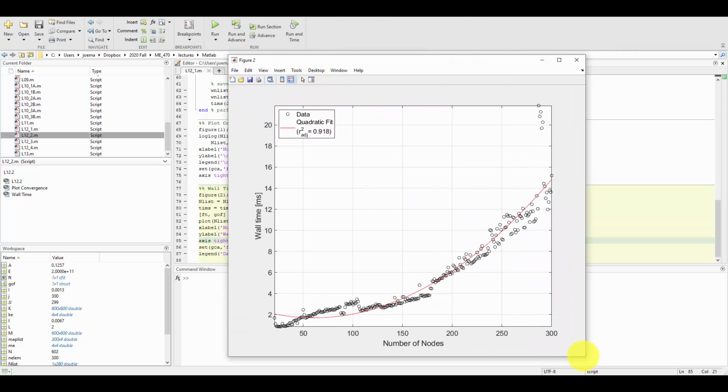So the exact fit is not too important here, but we just want to realize that adding more precision, adding more accuracy to our natural frequency, is coming at the cost of taking a little bit longer to run. Now, this is in milliseconds. It runs really quickly here. But if we scale our problem up, make it more complicated, it can start to run more slowly. But we do want to make sure that we are reaching convergence before we start doing any further analysis in our problem.